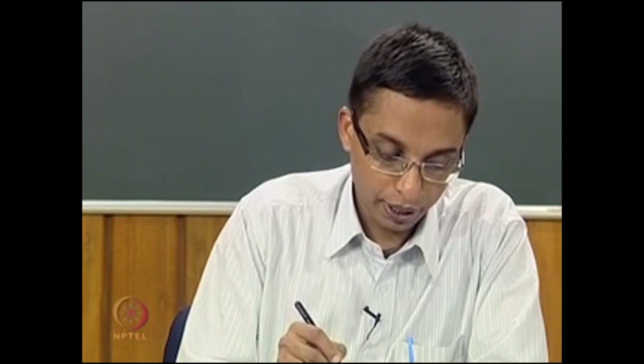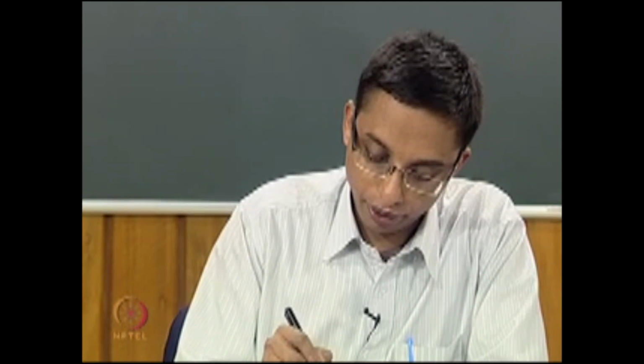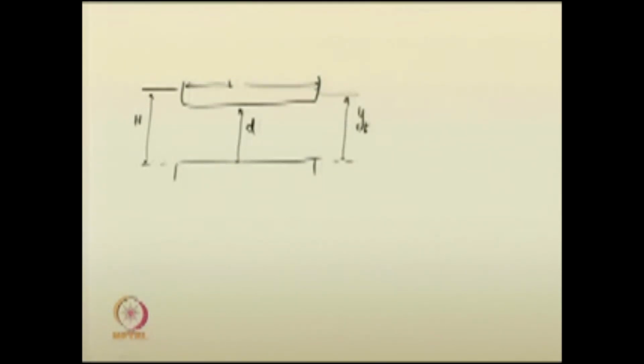Usually, again I am just redrawing the same thing. So, this is the length of the culvert and this is the depth of the culvert. Capital H is the headwater depth, and let this here be the tailwater depth YT. And let the slope of the bed of the culvert be S0. The flow occurs from this direction to this direction.